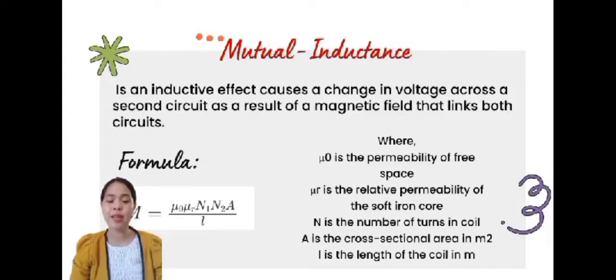If we increase the number of turns in the secondary, the intensity of the bulb also increases. If we cut down the number of turns to half, the intensity of the glow also decreases. From this, we can conclude that there is a relation between the EMF produced by mutual induction and the number of turns.